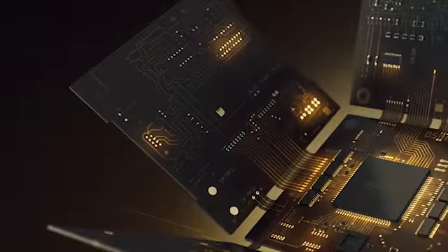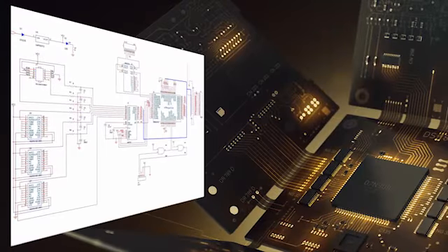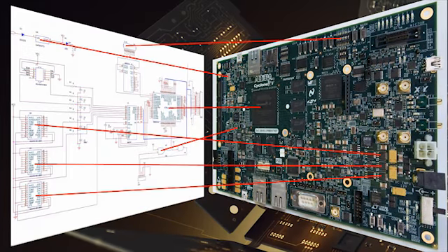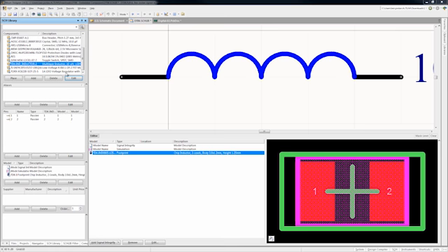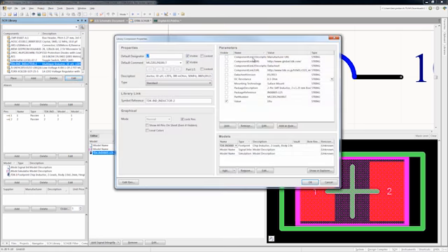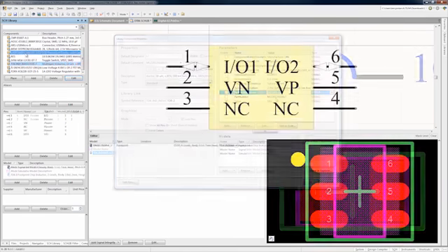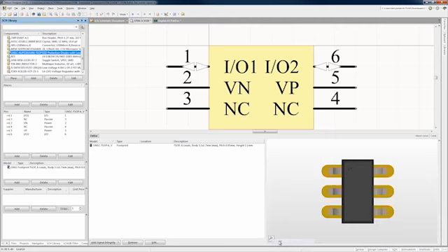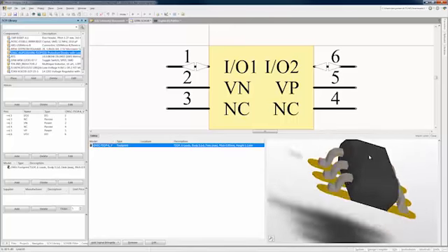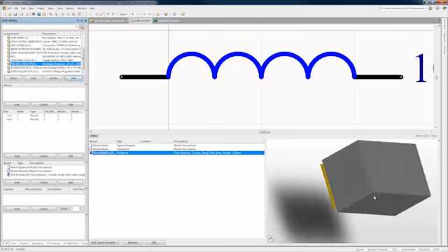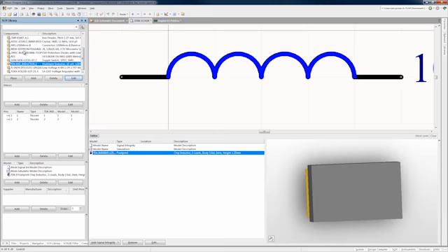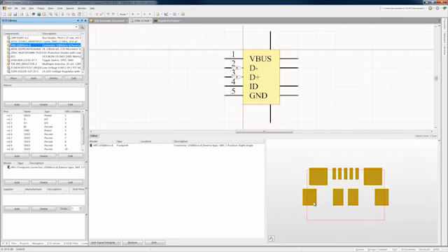Have you ever been frustrated by having to manually link parts from the schematic to your library of decals for the PCB layout? Even if you're used to doing this, you could be saving a metric ton of time with Altium Designer's unified component model. Every component contains its schematic symbols, bill of materials and other parametric data, PCB footprint with embedded 3D mechanical model, and even SPICE and SI models for verification. By using Altium's unified component model when you execute the ECO from schematic to PCB, you can be confident that the correct PCB decal and 3D mechanical model is used every time.